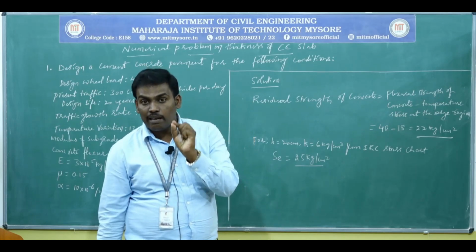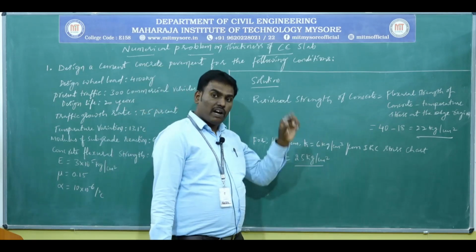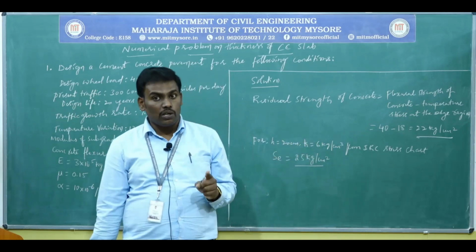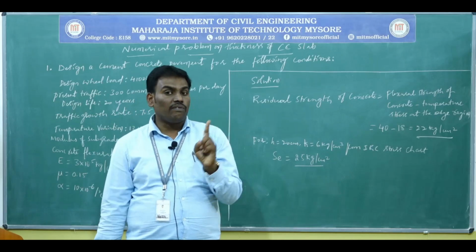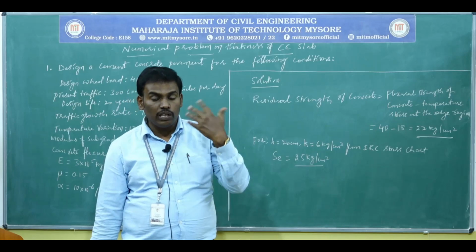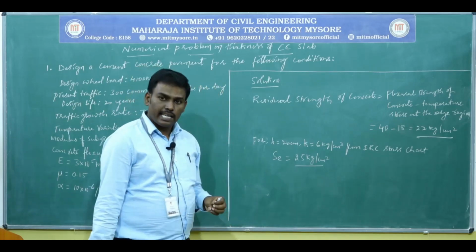Why I am saying that almost means, okay, after finalizing from available factor of safety, then you need to check for corner load stress, then you need to check for correction based on the traffic data. Okay, then only finalize the design thickness.